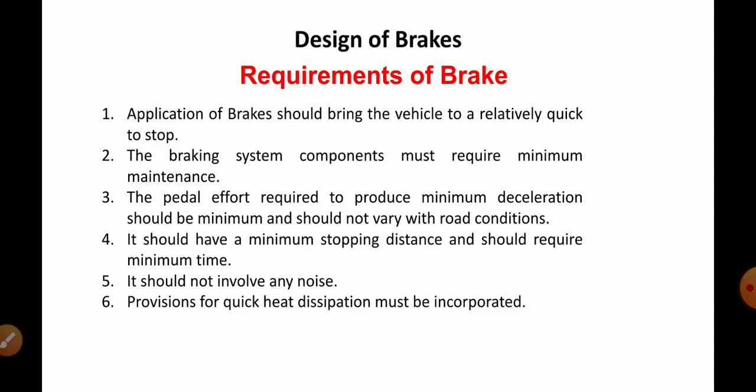The pedal effort required to produce the minimum deceleration should be minimum and should not vary with road conditions. It should have a minimum stopping distance and should require minimum time to actuate. It should not involve any noise. Provisions for quick heat dissipation must be incorporated in the brake system. So these are a few requirements of the brake system.